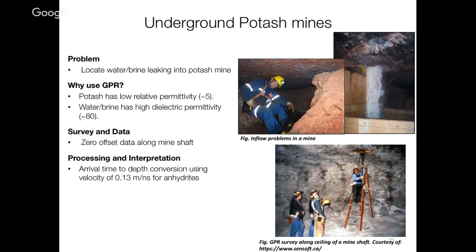Anyway, there's layers of water above you, and you're mining this stuff out, and at some point something might crack through, and first thing you know, you've got water like that. So you want to be able to see, okay, where is the water above you? So you can take a GPR unit, and you just put it up on the ceiling, right? And now you're doing a GPR experiment, but you're actually looking up this way, which is what they're doing here. So it's logistically more difficult, of course, but still you go across and get a GPR radargram and then see what you got.